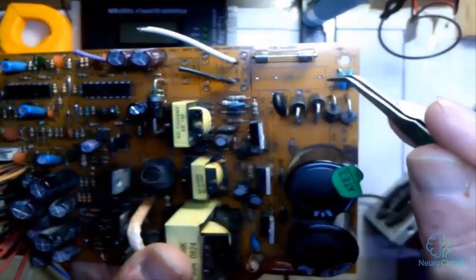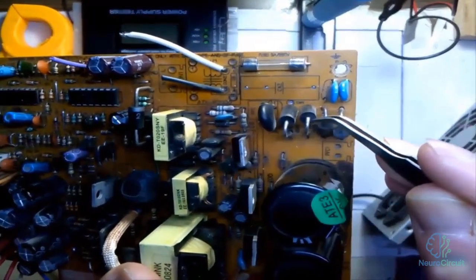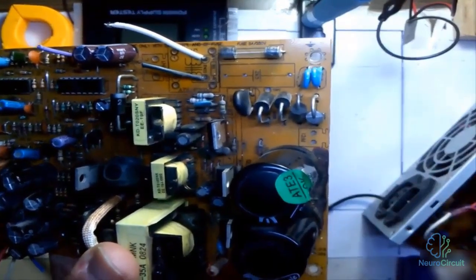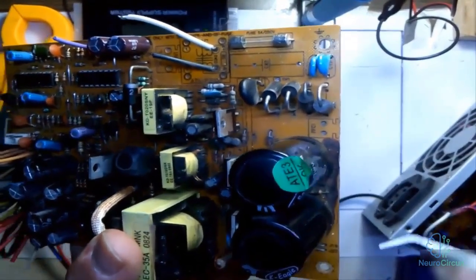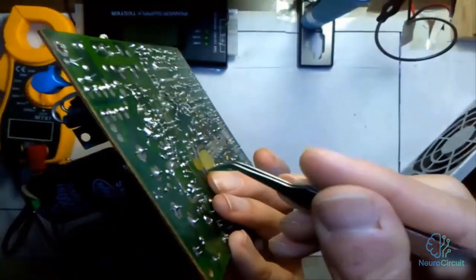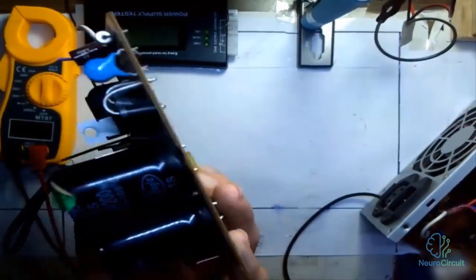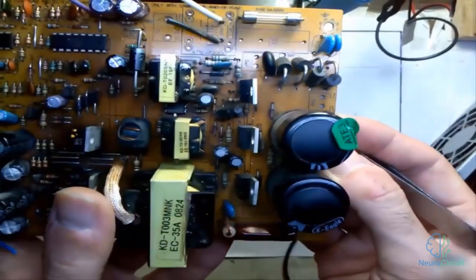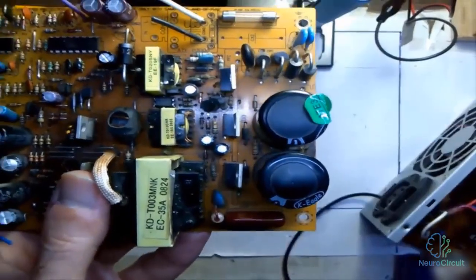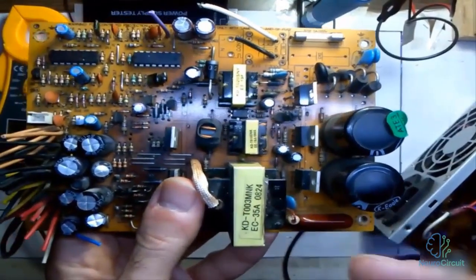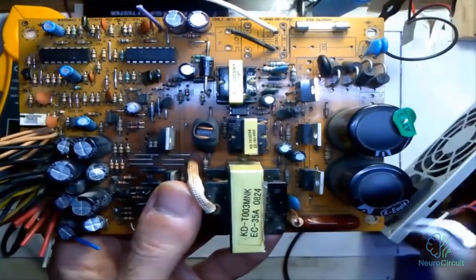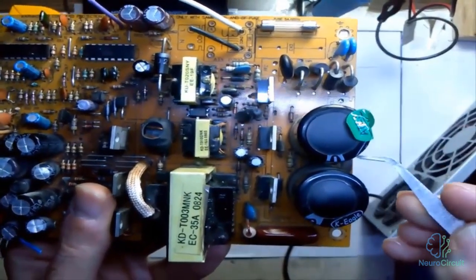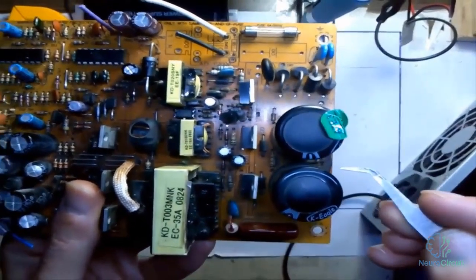So the 220 volt AC power enters the bridge rectifier, and when it's converted to DC power and comes out, its voltage actually increases a bit, and if you use a multimeter to measure the voltage of the capacitors, you'll see that the multimeter will show you a voltage of around 270 or even 300 volts, which I'll demonstrate for you practically right here after the explanations, and in the next sessions if we don't get to it in this one.